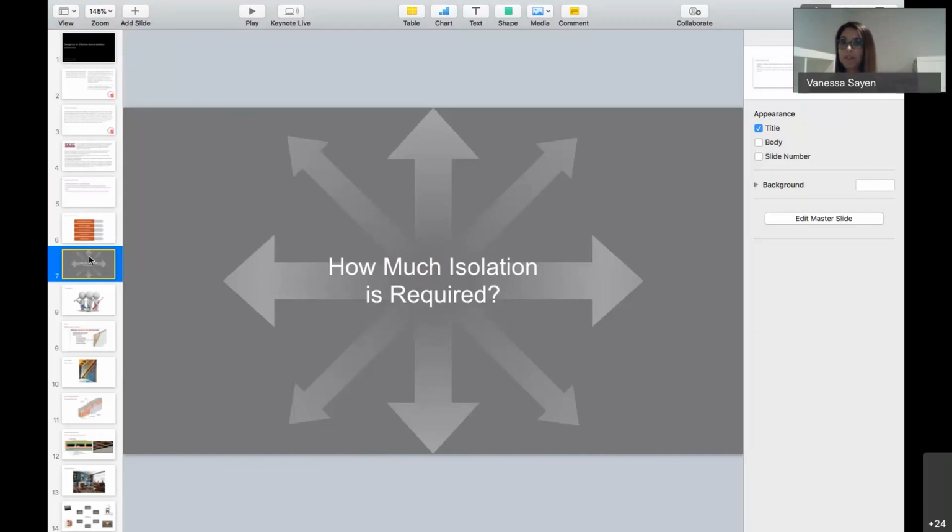So let's say you have a small office in your house, or maybe you're working in a commercial setting where there are offices and they need to keep privacy. These types of rooms are going to require treatments that attenuate the middle frequencies. Isolating a room for a music system or a home theater requires certain construction techniques that block low frequencies. So right here, we have two different examples: an office setting or something more personal that is going to be covering the middle frequencies, and again, in a home theater environment, we're more concerned about the low frequencies of the music and how they travel.